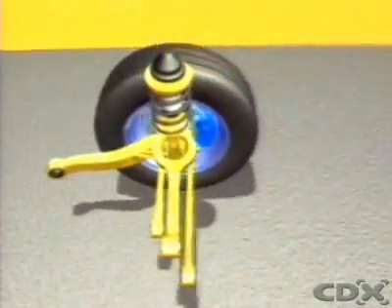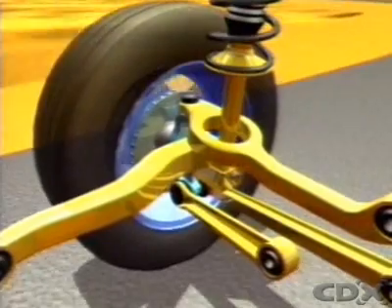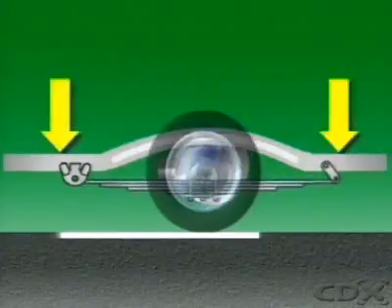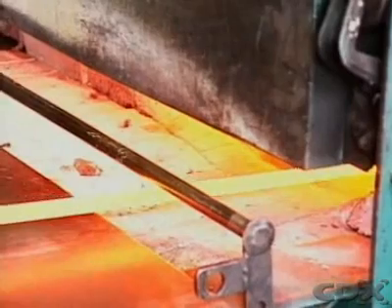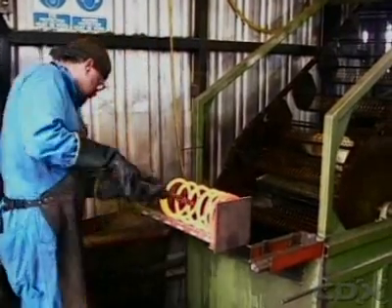The springs are located between the frame and the axle assemblies and are shaped to suit the application. Leaf springs are normally semi-elliptical, and they absorb the applied force by flattening out under load. Coil springs are formed in a spiral from a single steel rod and absorb the force of impact by twisting.